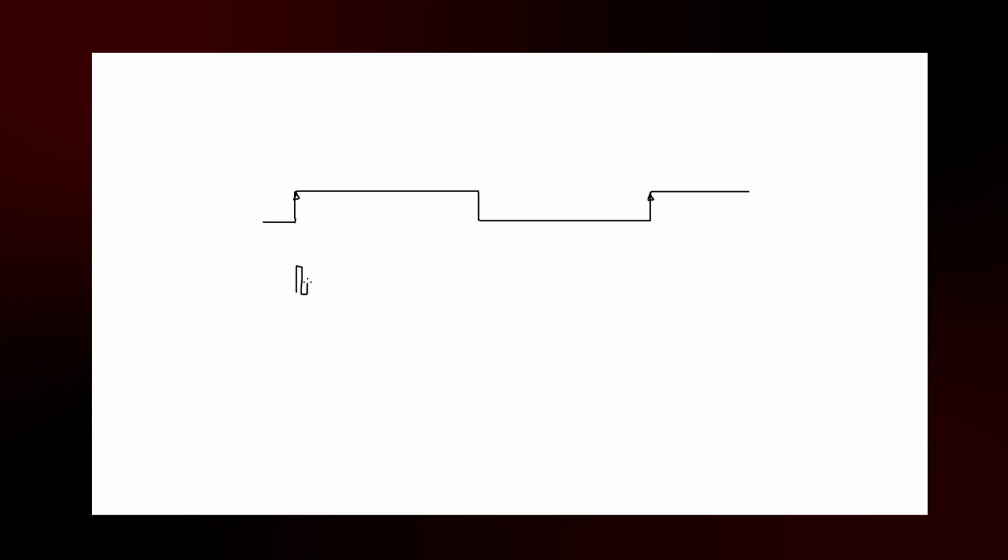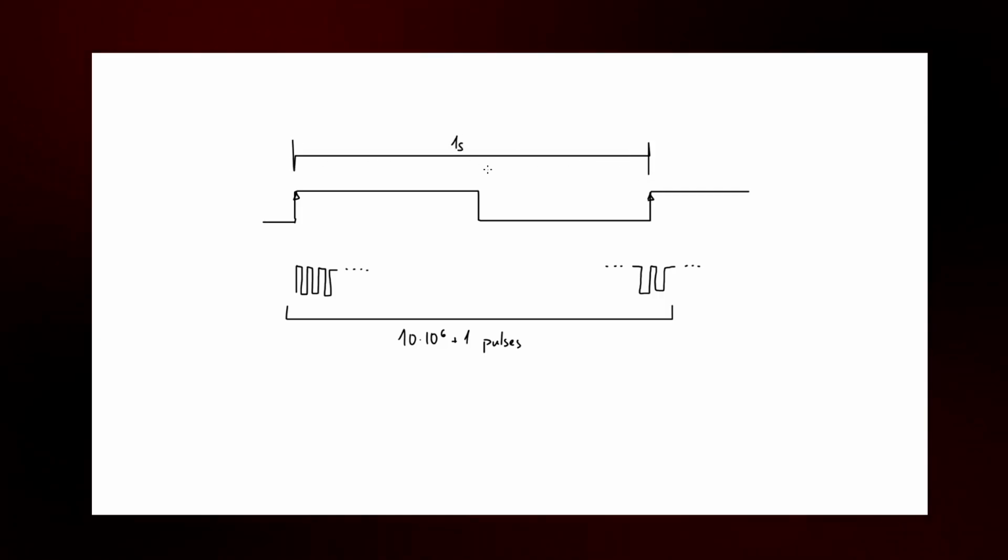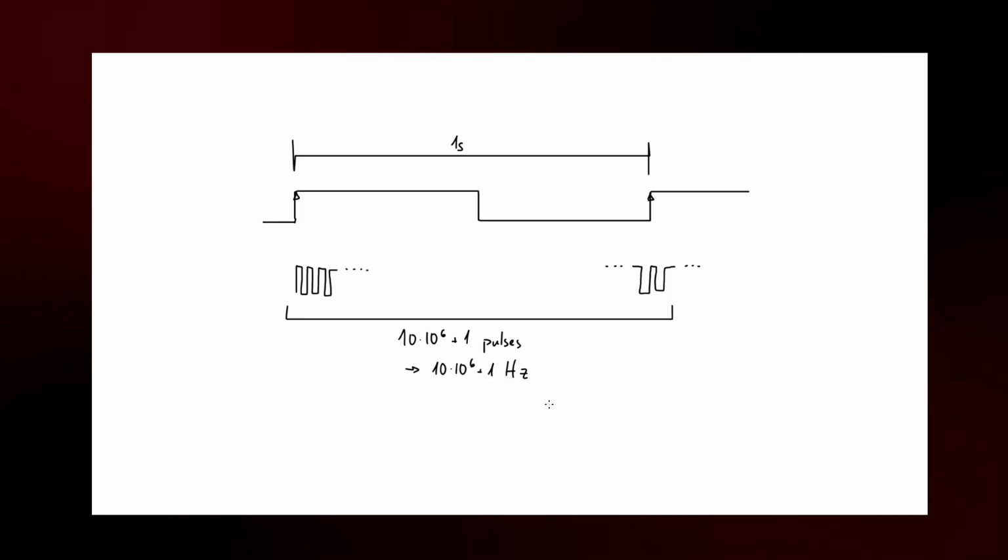About getting the actual frequency of the OCXO, we can count the number of edges received from the OCXO in between two edges of the external PPS. For example, I receive a rising edge on the external PPS. My device starts counting the OCXO's edges and it stops when another external PPS is received. Let's say that I see that 10,000,001 pulses have been received. From that, we can deduce that the frequency of the OCXO must be really close to 10,000,001 Hz. Easy enough, now I have a way of getting the actual frequency of the OCXO.